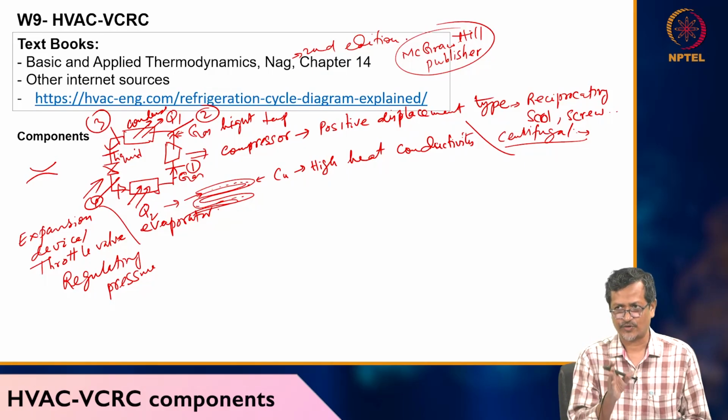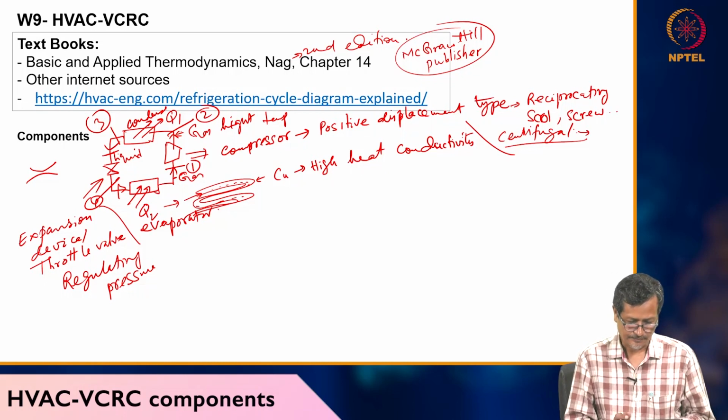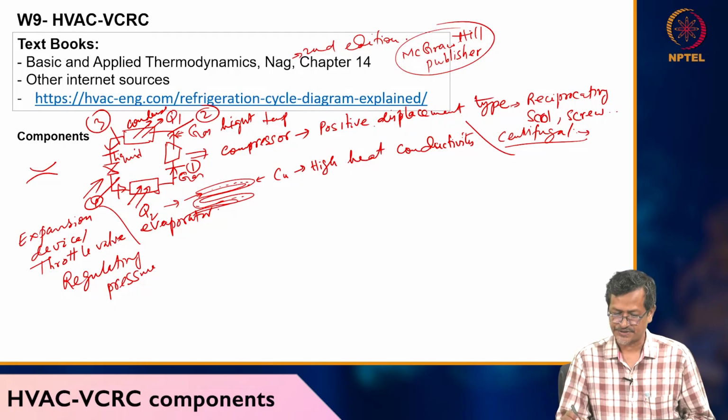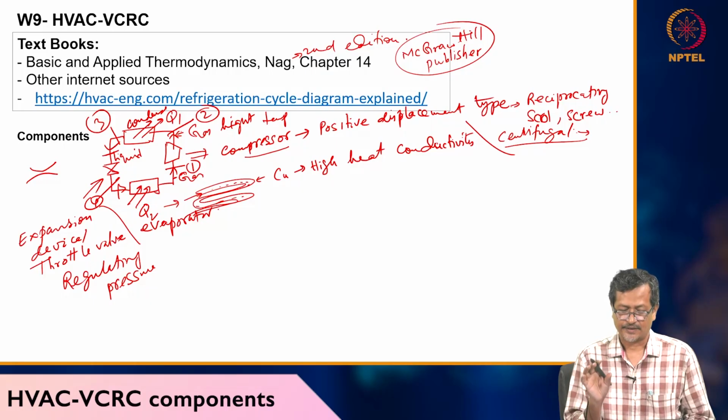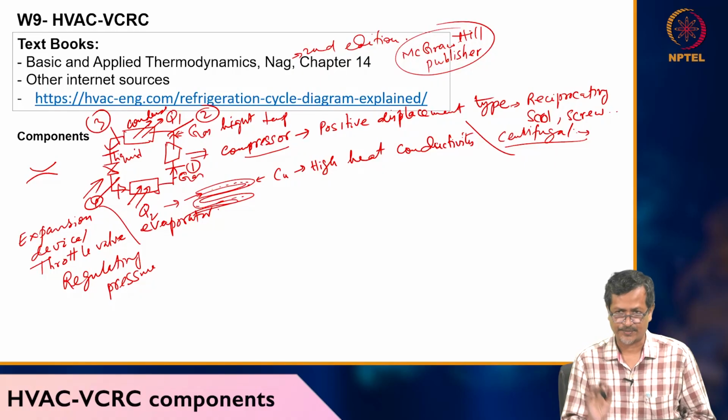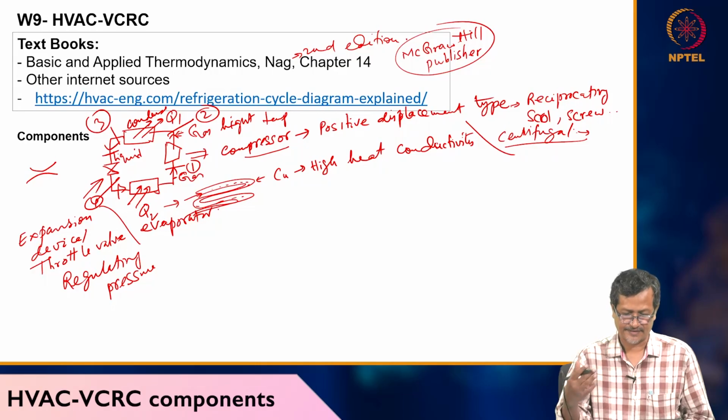Because they will be optimizing your energy requirement and noise production. In a compressor system, the name is compressor, so it will not be handling any liquid. Normally you have to give gas, or after the evaporator everything should be gas, then you put that gas into the compressor system, then you are compressing, releasing heat in the condenser, and it is passing through the throttle valve.